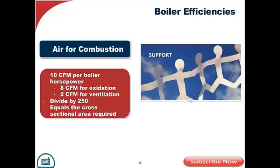Now, that's not to keep the boiler operator comfortable. It's really to make sure that that room does not go negative. Then you take that, let's say we've got a 300 horsepower boiler, we need 3,000 CFM of air. You divide that by 250, and that will give you the cross-sectional area in the room that we need for ventilation.